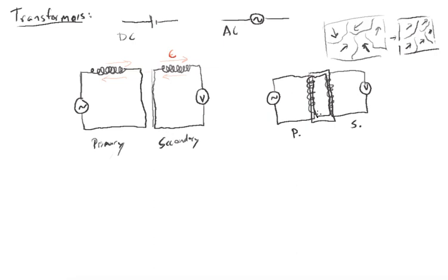So essentially what happens is you get what are called little eddy currents that get produced inside here, and it lines it all up and just adds on to that. But these eddy currents will occur in here too as the magnetic field goes through it. Basically eddy currents are a little response to it, where little currents will form inside the material itself. These little currents will flow in little circles in order to counteract the flux, because you also have to think you're changing the flux through the iron core, and that actually tries to then counteract the magnetization of this ordering of the cores. You get these little currents that produce counter magnetic fields that start to cancel it out.